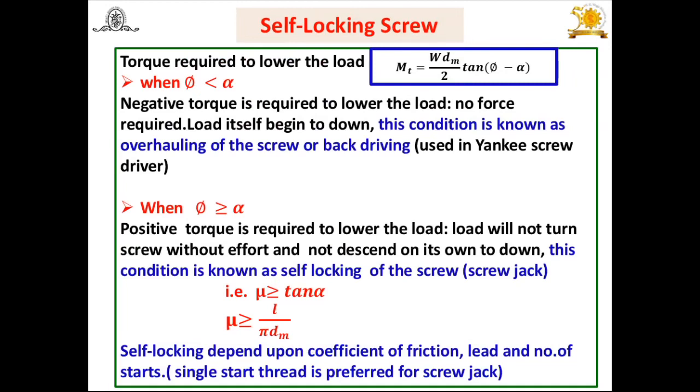In case of power screws, screw jacks or other devices, you will find self-locking plays an important role. And how to achieve it? Many times the applications of the power screw are based on a high efficiency requirement or low efficiency, but you will get self-locking at the lower efficiency. We will see this when we derive the expression for efficiency of the power screw. Before that, let us see what we mean by self-locking.